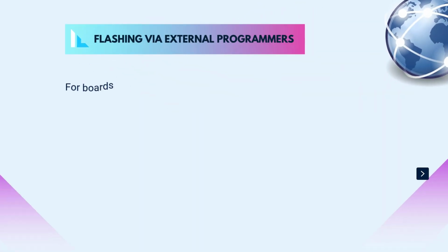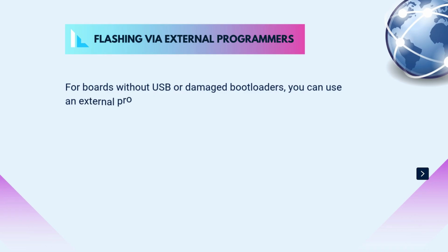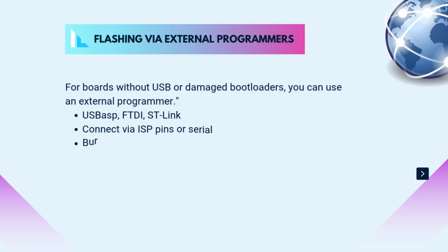What if your board has no USB port? Or what if its bootloader is corrupted? In such cases, external programmers come to the rescue. These are devices like the USBasp, FTDI Breakout, or ST-Link V2.